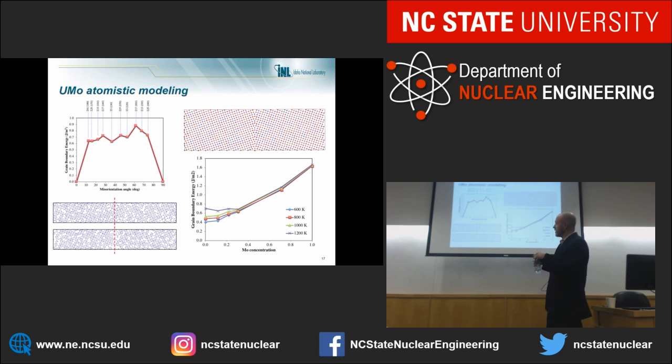We did a very fundamental grain boundary study in these systems, looking at the grain boundary energy as a function of the misorientation angle, and looked at a variety of high angle grain boundaries in these systems. We compared to older studies where they tried to calibrate some research with experiments. It wasn't exact, but our results compared very favorably to previous work that was done.